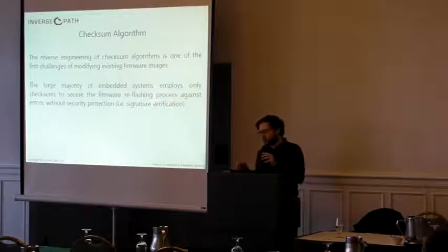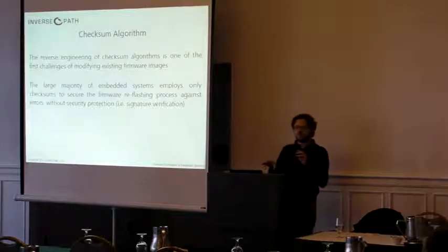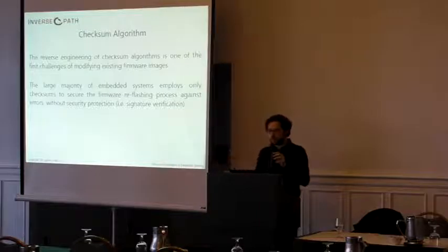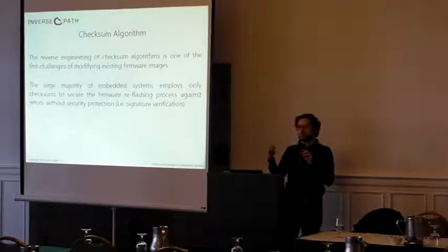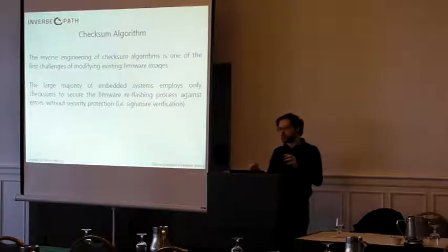approach, because there have been cases where we thought that the checksum was located for verification purposes in one specific location, and in some systems the checksum was actually included twice in other memories. And you risk breaking your system if you upload a firmware which doesn't match both checksums. By using collisions, since you're creating or modifying an image with exactly the same checksum, you're good to go and you don't have to worry about that.